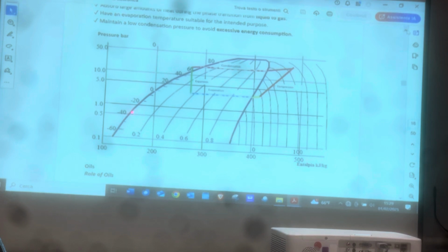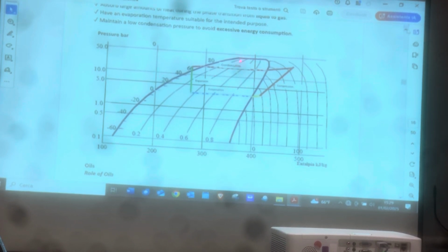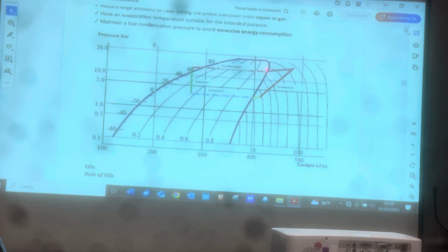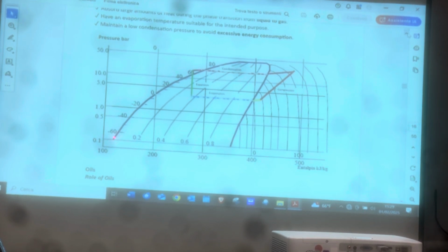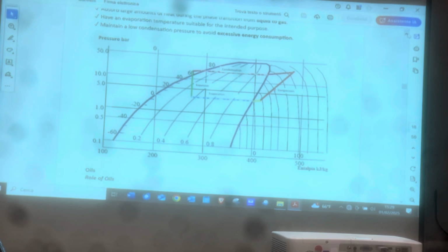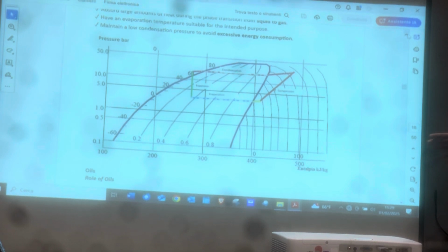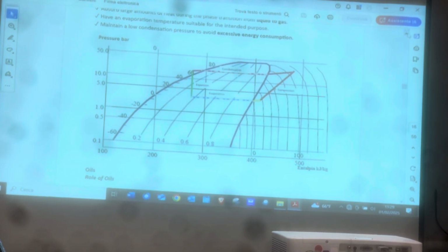This is your saturation line. This is your critical point. This is your condensation line. I think in American they call it the dew point. And this is your superheat, and it's going to be the, no, that's the dew and that's a bubble. Yeah, so, anyway, I might be wrong with the terms here. In Europe we use different terms.